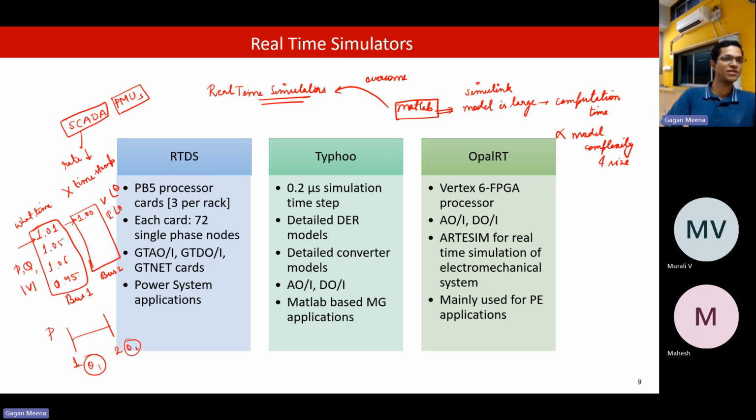That's why the PMU was introduced. Here each data point is measured using these sensors, these PMUs. They have a GPS-based timestamp. We know at each bus at what time what data has arrived. Then we can easily compare them.